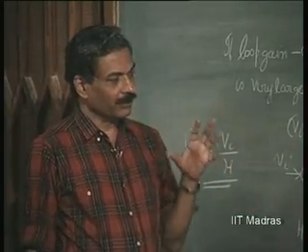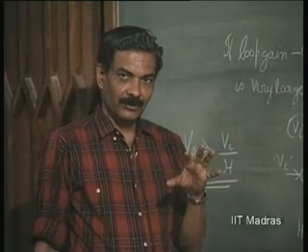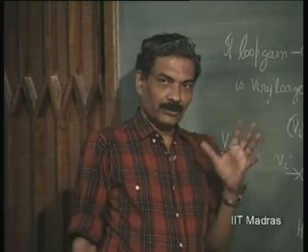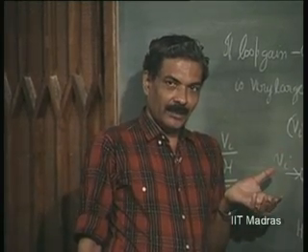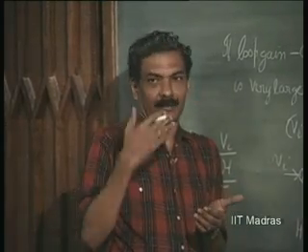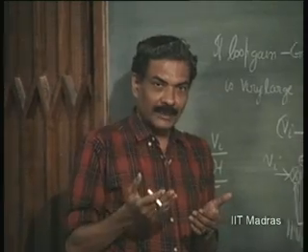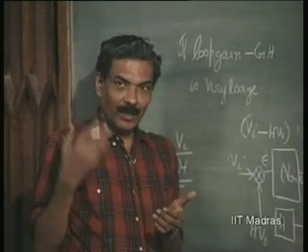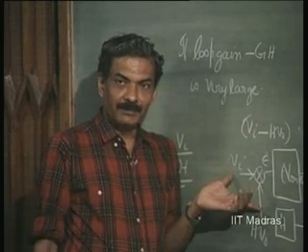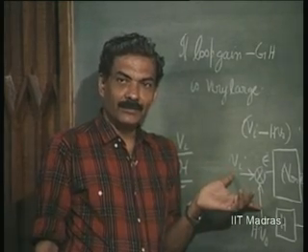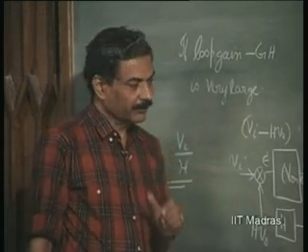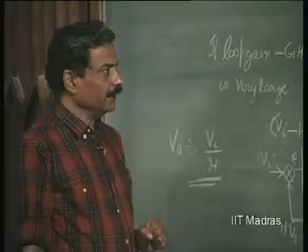One thing, however, you should note is the gain is reduced, and therefore, the voltage level that is required at the input to bring the output to the same level as before is going to be higher, but even though it is higher, for the same output level now you have lower distortion in the case of negative feedback amplifiers than in the case of open loop amplifiers. So, this is to be borne in mind. So, linearity is improved.